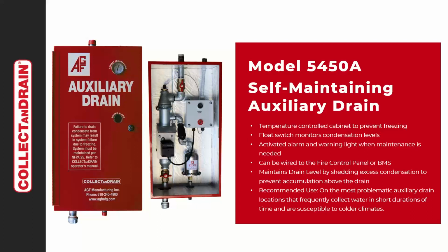It comes like our other collect and drain products, in a heavily insulated steel, heated cabinet. It has alarm functionality, so that if the system were to trip and flood, it will chirp and blink locally, as well as send trouble alerts to your fire panel or building management system, telling you the unit is completely full. But it is a heated cabinet, so you don't have to worry about it freezing and breaking.